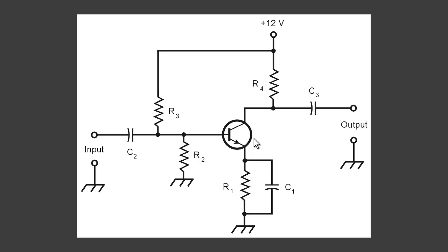So the only choice that makes any sense here is choice A, below its alpha cutoff frequency. Now the alpha is a completely different specification in a different kind of circuit, but in general, if we go far enough below the alpha cutoff frequency, we can get considerable dynamic current gain. So choice A works. Choices B, C, and D just don't make any sense.